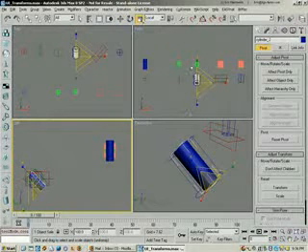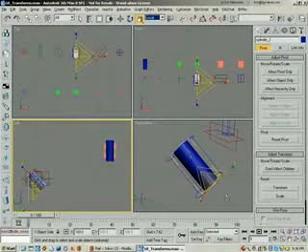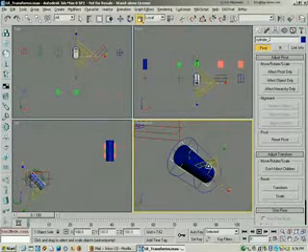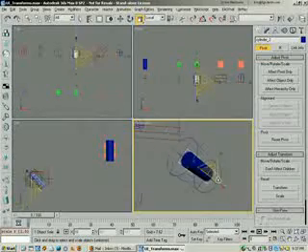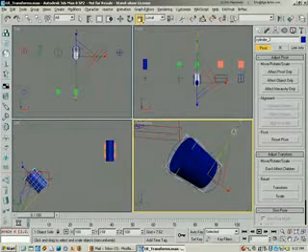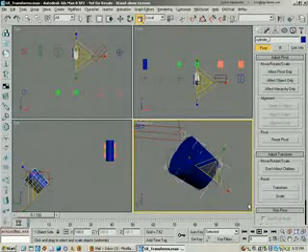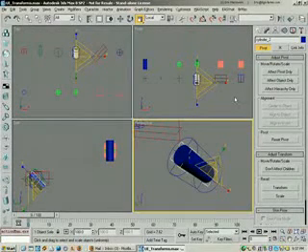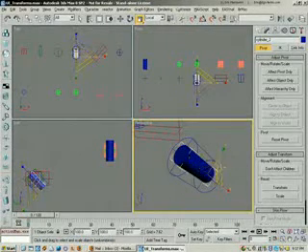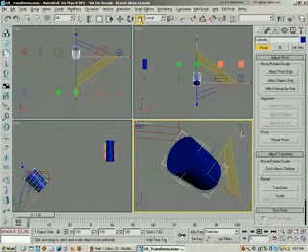And now I'm going to scale it to fit the correct size. So it's already set to local, which is great. And now to adjust the radius of this, if you notice, if I click and drag in the middle, it scales up the whole thing equally in all directions. Scale in one direction, sure, that could work if you then go to the X, but it's not really precise. You're not exactly guaranteed that it's going to still be a circle up here at the top. But what we can do is click and drag on a little strip that combines the X and the Y.